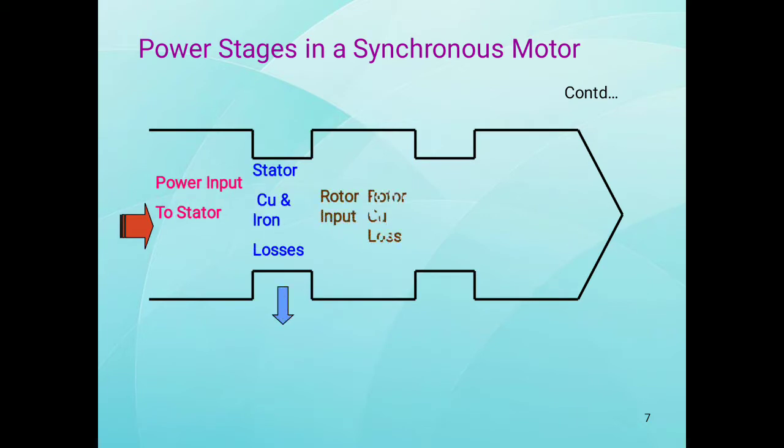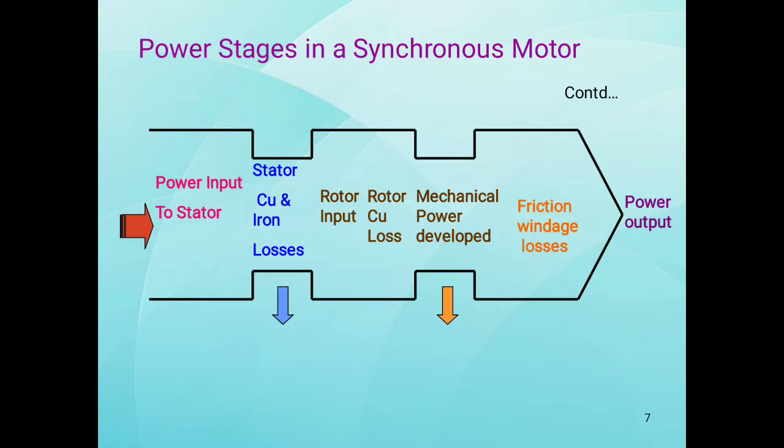See here: power input, stator copper and iron losses, rotor input, rotor copper losses, and then mechanical power developed, friction and windage losses, which gives the power output.